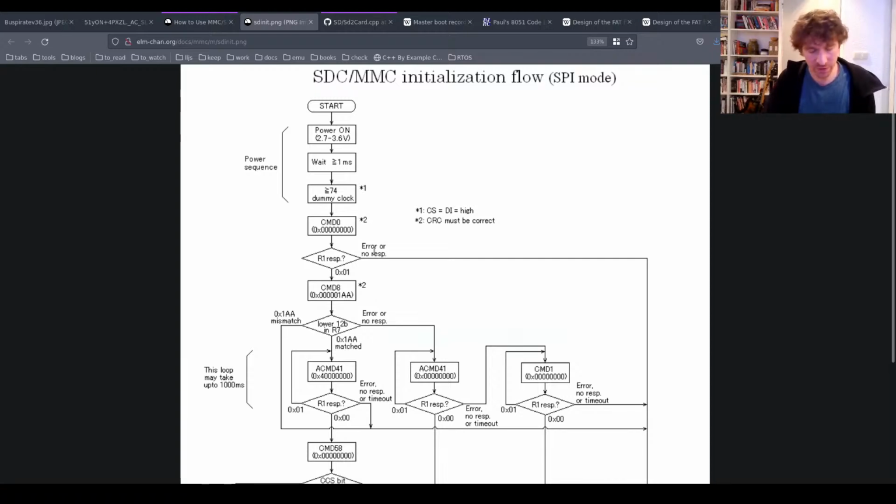And then we're going to do await this.spy. No, not this.spy. This is going to be our first abstracted thing. This is going to be our send command. I think I'm going to rename that to SD send command, so it's clear that it's an SD card command. Oh, lost it. All right, so the command we're going to send is command 0 and the argument is 0.